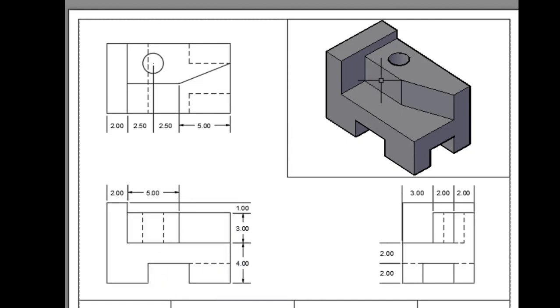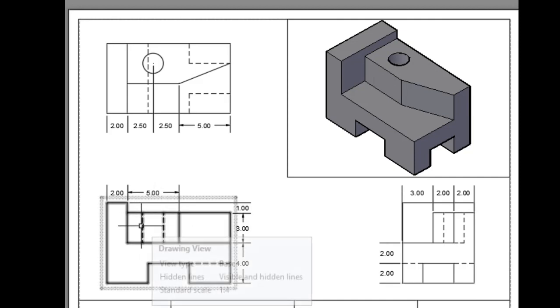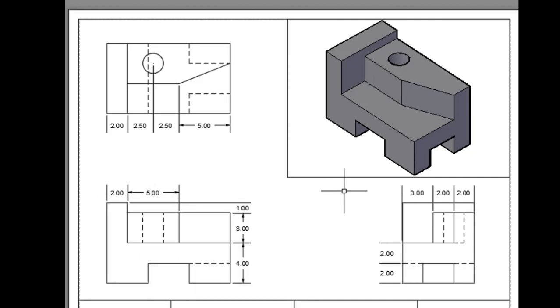So that's if you're looking through a surface at like a hole behind a surface, then you would see it as a hidden line. So the circle cylinder shows up as a hidden line, as do these rectangular cutouts on the top. So we have a slot that goes all the way through.